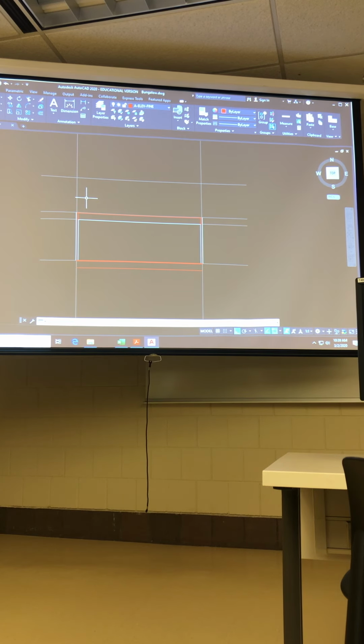So from that end point, I am now going to press the shift key and 2, which brings up at, and now I'm going to enter 12 feet, comma, 10 feet. And voila, it has drawn a 10-12 roof pitch for me.